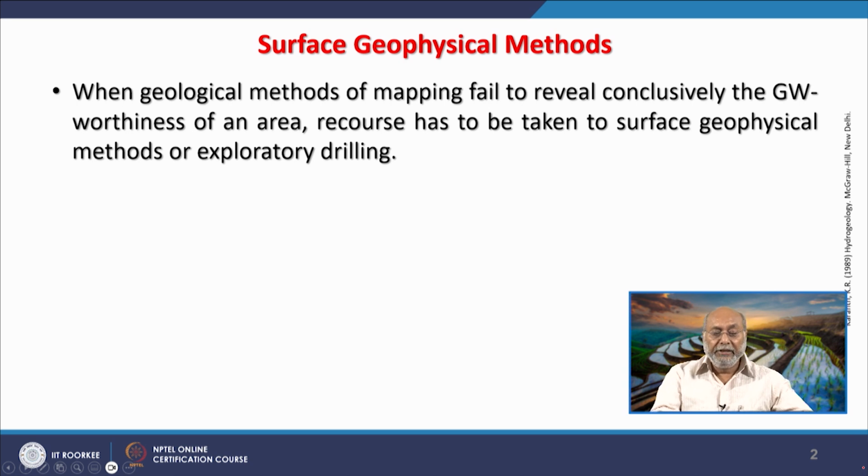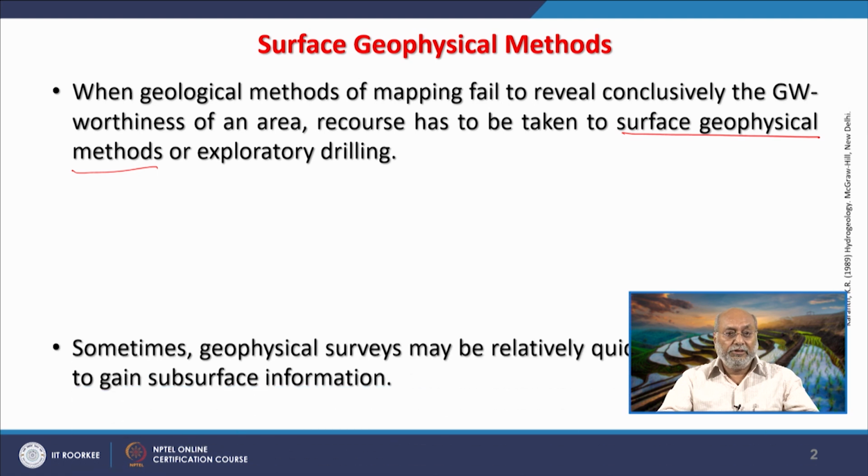So, when we are not getting good information from geological methods, we resort to the surface geophysical methods, or maybe in this we might go for some exploratory drilling, not exactly test drilling, which is sometimes not very deep, but initially we would like to know what the near surface geology is.